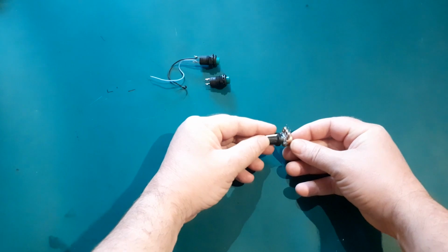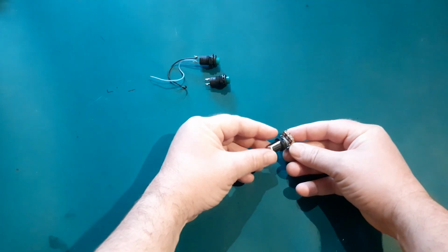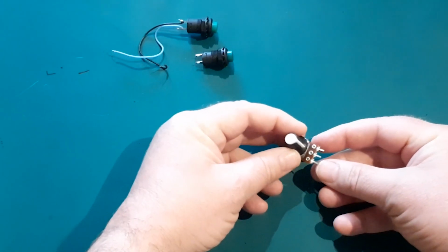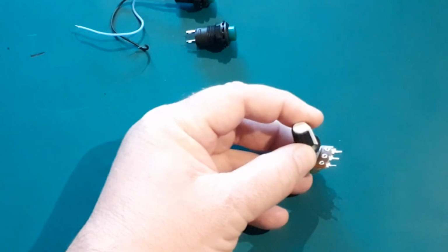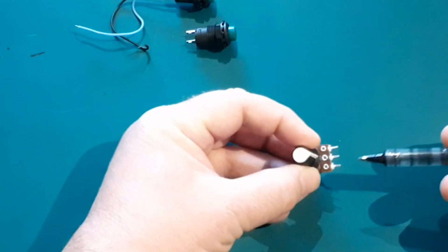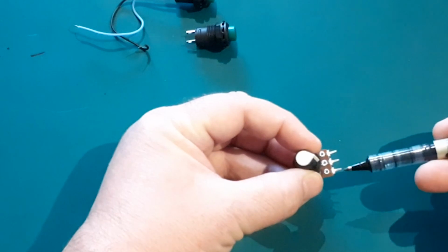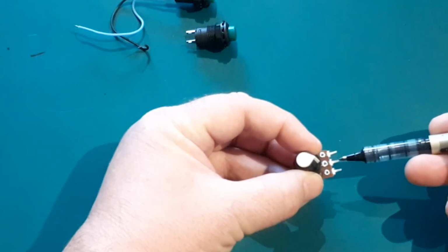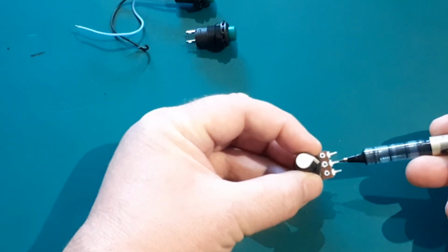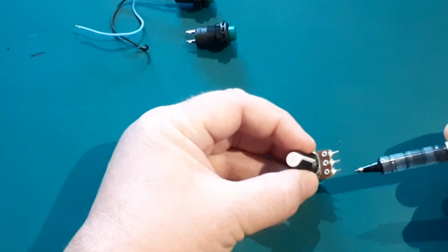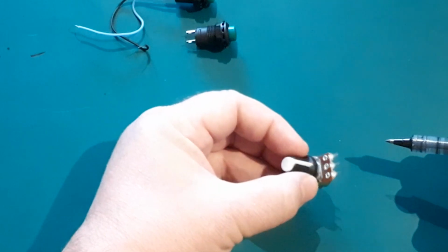The reason it doesn't matter what the value is, apart from the caveat I've just mentioned, is because we are going to wire this as a potential divider. As you can see, there are 3 connections. We wire one side to ground, one side to VCC, then the middle will actually put out a voltage that is proportional to the position of the dial. Cool, eh? Well, it is for people like us anyway, isn't it?